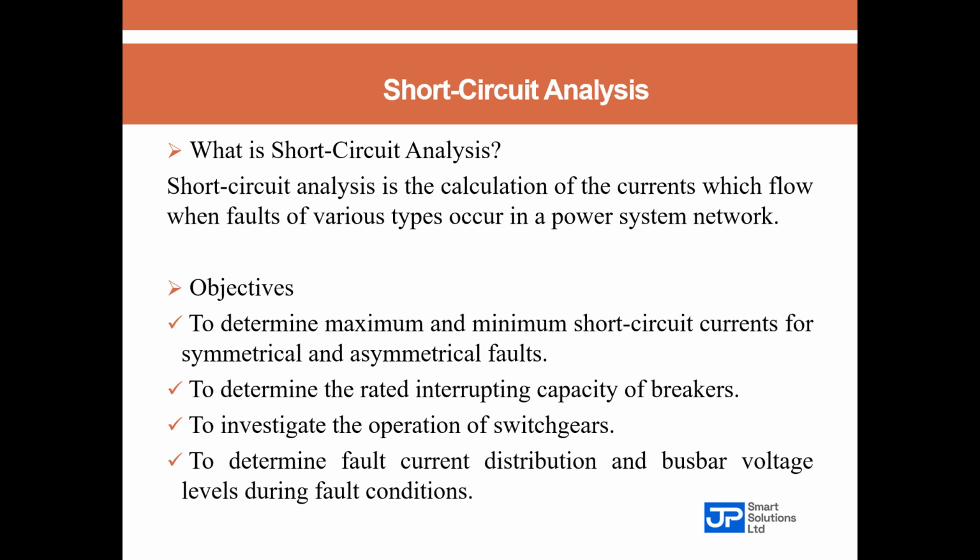All right, let me share an instance. A contractor installed a brand new low voltage switchboard for a client. Now, as usual, everything tested fine, insulation, continuity, all good. But then, when a cable fault occurred, the circuit breaker exploded like a grenade. Why did this happen? A root cause analysis was carried out, and it was observed that the available fault current from the utility was 30 kiloamps, while the breaker was rated at 18 kiloamps.